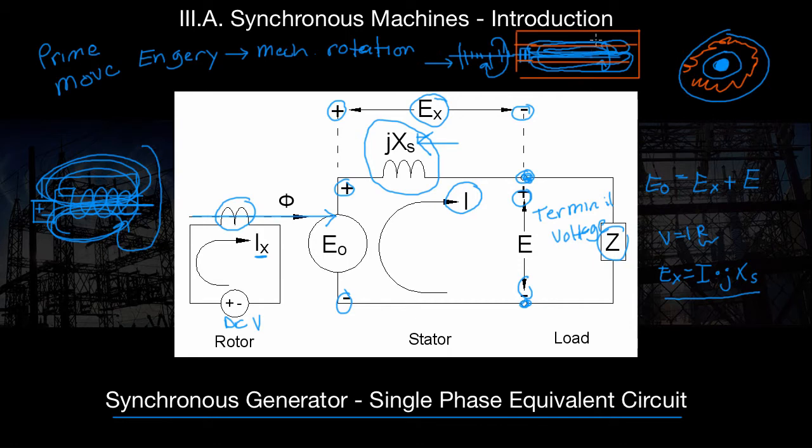Anyways, you also have windings in your stator. Your stator is one big coil. Think of the stator of a motor. In that stator you have your three phase connections, which we'll call A, B, and C. Now this is a rotating field because our rotor is excited. As this rotating mechanical field induces a voltage in our stator coils, that produces power.